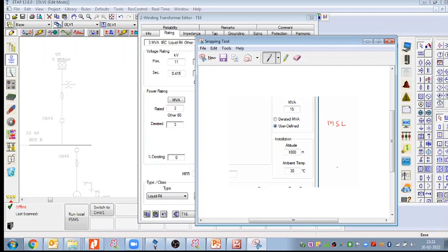If you go to any railway platform, every railway platform has its height from the sea level mentioned, how much height that platform is from the sea level, and based on that the entire traction system is designed, right? So if I change this installation height, which is 1000 meter, and go to any hilly terrain, and we change this altitude, then what will be the impact on the transformer?